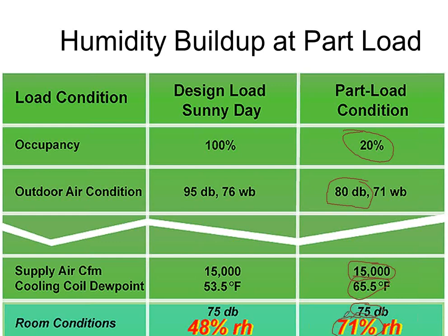If I have 70% humidity for about 2 weeks, I can grow mold. If I have 80% for like 3 days, I'll start growing mold. So I really do want to try to keep it below that, and having better staging on my equipment, changing the airflow like we're going to talk about in a couple minutes here, or adding in an ERV are all ways we can really improve upon that.